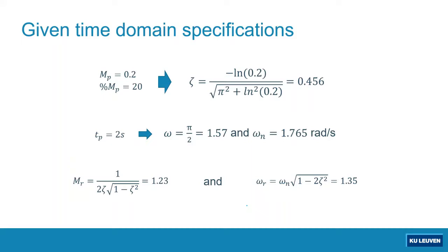So let's consider I have an underdamped second order system where, after I give a unit step input to that system, the response shows 20% overshoot. From one of the formulas that we discussed in the unit step response in our previous video, we can find that zeta, or the damping ratio, is simply a function of percent overshoot.